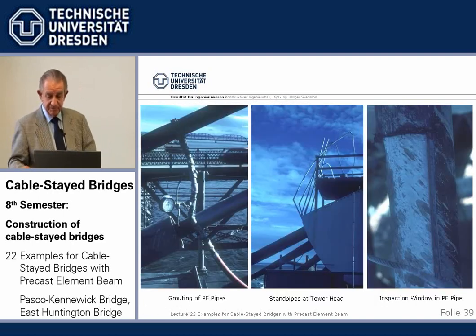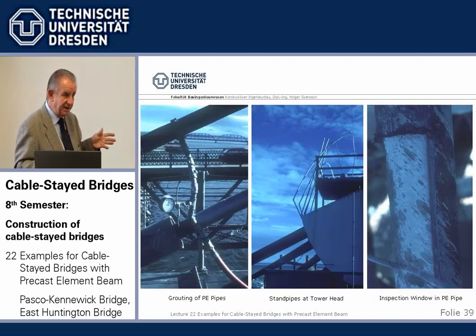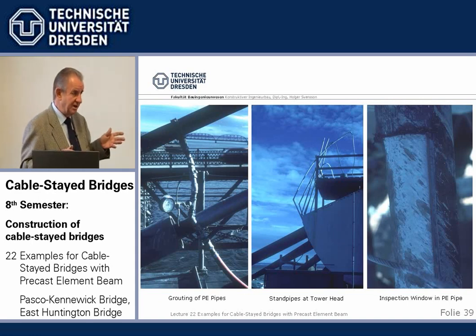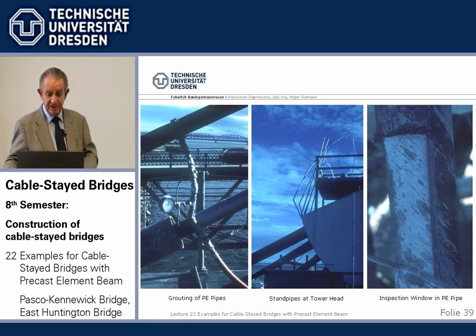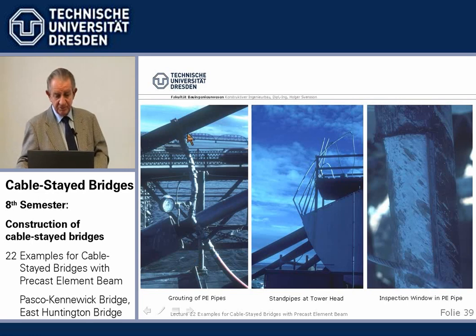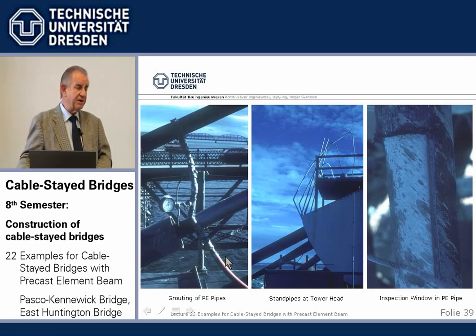Now, for the initial cables, a little tedious way of inserting the cement grout for corrosion protection. It was empty. So what we do is we have here a pressure pipe, similar to how we grout tendons, a pressure pipe with the grout going, of course, from bottom to top.